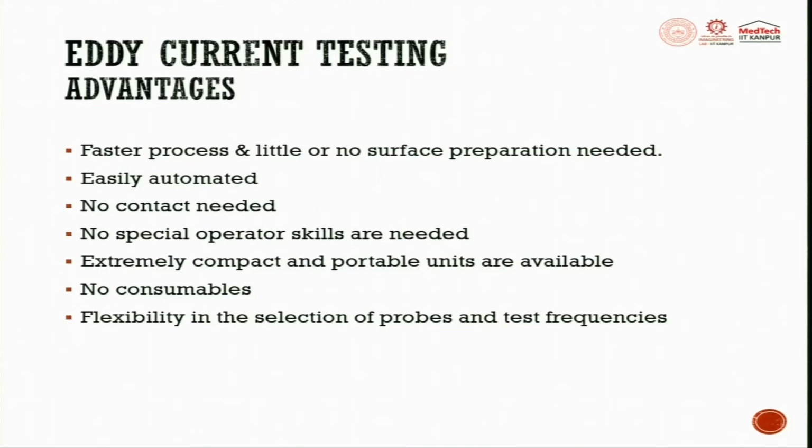The advantages are that it is a faster process and little or no surface preparation is needed. It is easily automated, no contact is needed, and no special operator skills are required. Extremely compact and portable units are available. There are no consumables as well, other than the probes, which sometimes have to be repaired time and again. We have flexibility in the selection of probes and test frequencies in eddy current testing. This flexibility is to suit different applications and different shapes of the components that we are trying to test.